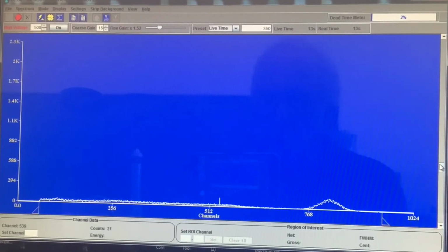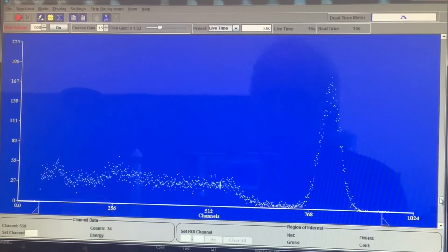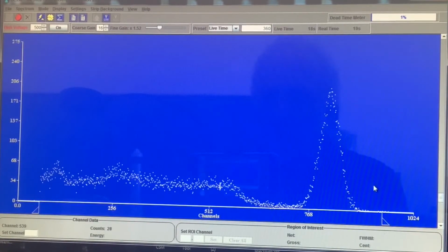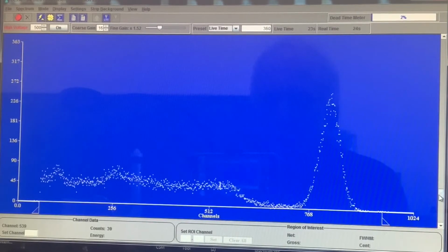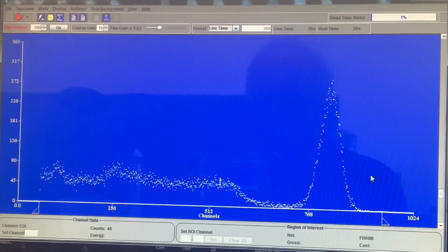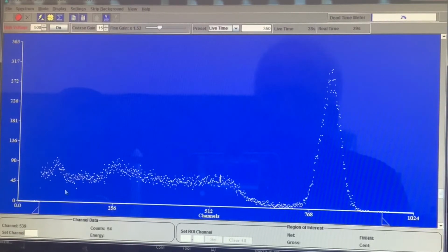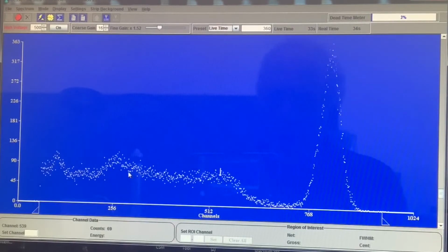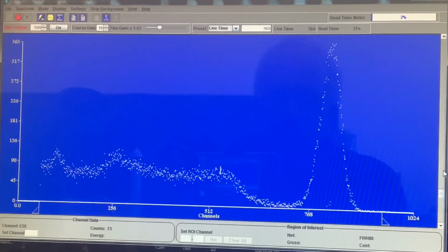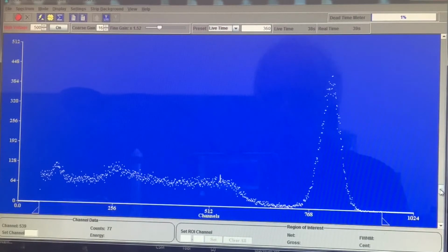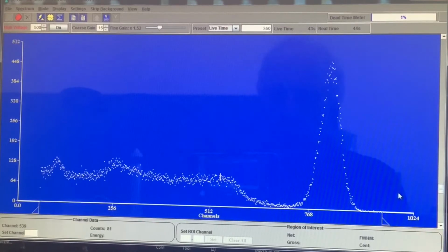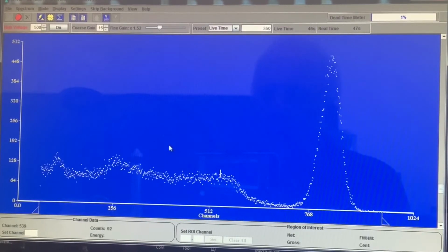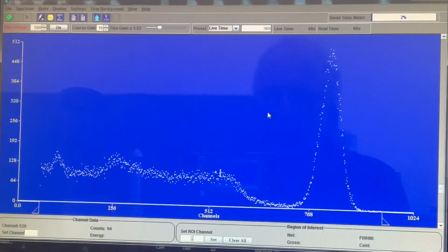by setting the gain. So the question is whether the resolution, the resolving power of the detector, depends on this amplifier gain. So as we discussed in class, we don't expect that it should. It basically took every incoming pulse and multiplied it by a gain value and moved it into a different channel number, and that shouldn't really affect the resolution of the instrument too much. But let's go ahead and verify that. We can stop our spectrum right here.